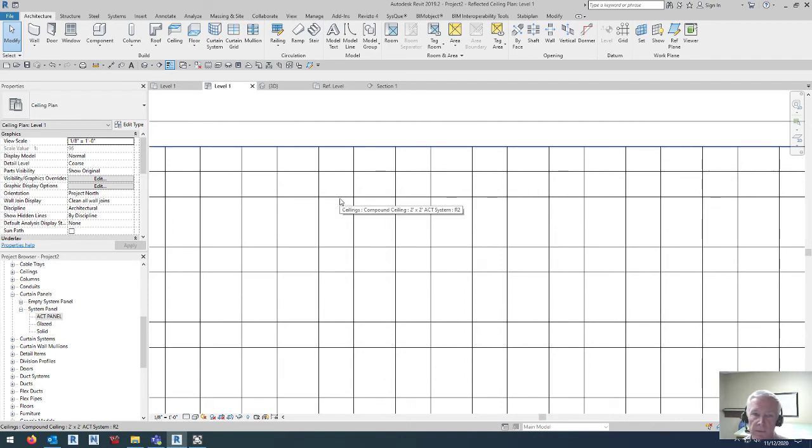If we're matching an existing architecture, if you're building this from scratch, you can make your adjustments here. But I would adjust the way you want your 3D ceiling to lay out before you switch it over to the actual 3D ceiling. In other words, leave it on just slope glazing with no mullions, because once you change it to mullions, you can't move them. They're all locked, and it really becomes a pain.